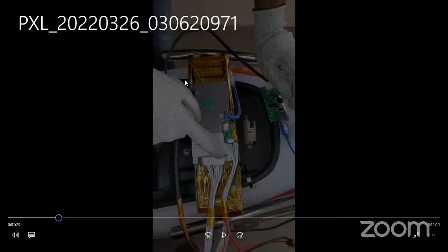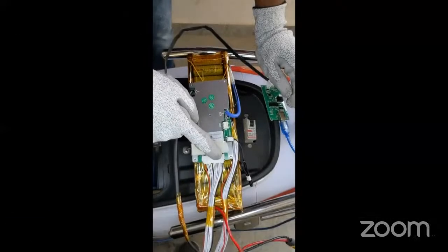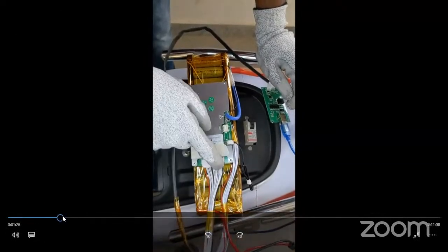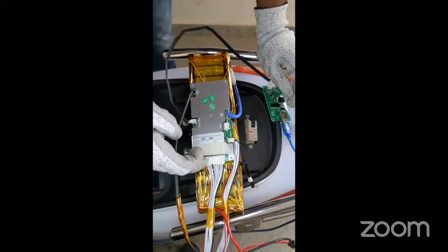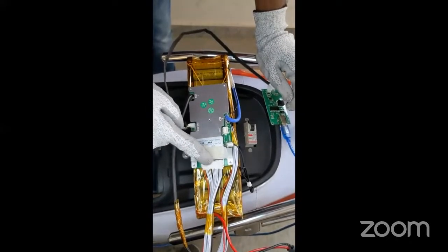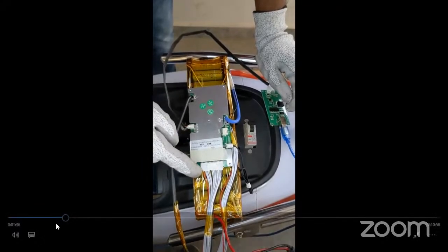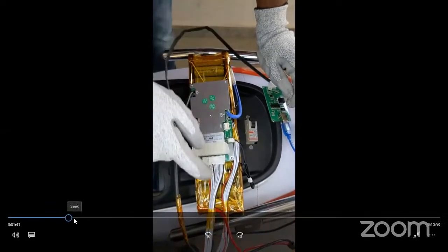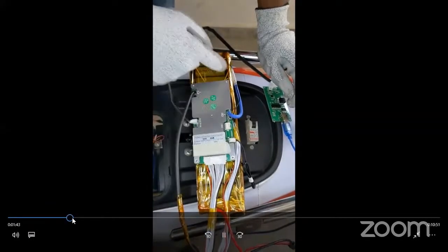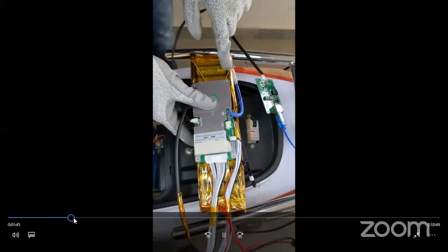Then you just collect the C minus and the battery pack main positive part, and you have the connector at the end. So now you can use it for either discharge or charge, which is known as BC0, the black wire, which will directly connect to the negative terminal. In total we have 14 wires, out of which 12 are white, one is negative, and one is positive, in red color. First you connect to the negative terminal, then in continuation you connect all the white wires, which you can see here have already been connected.